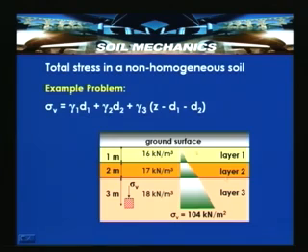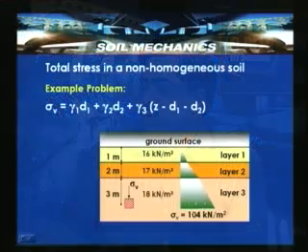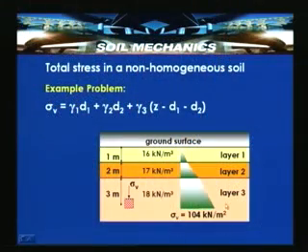So, in that case we can determine the resulting vertical stress, which can vary like this, and there is a chance of varying slopes because the unit weight is changing. So, there is a change in the variation or slope of this vertical stress with the depth variation. So, sigma V is equal to, here what we determined from this example, 104 kilonewton per meter square.